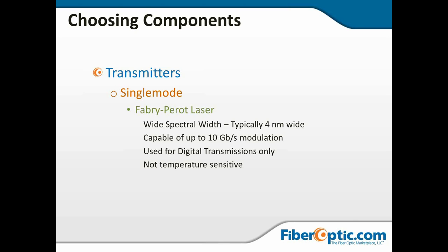And it is not, it says on the slide, not temperature sensitive. More appropriately, it's not extremely temperature sensitive. Any light source is going to be, to a certain degree, temperature sensitive, and even a Fabry-Perot laser will burn up if you don't control the temperature in its environment.